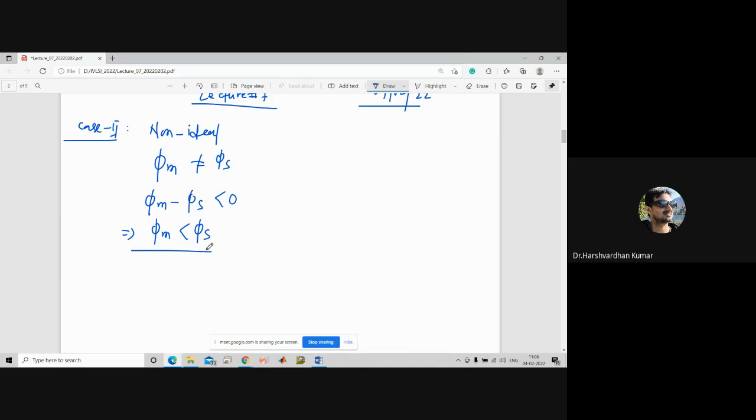So now what will happen in that case? We have to check what the band diagram will be now. Will it be flat or tilted? Can you guess? Tilted, right? Because here the work function of the metal is quite a bit less than that of the semiconductor, so at the metal side it will be quite less. So let us draw the energy band diagram, tilted like this.